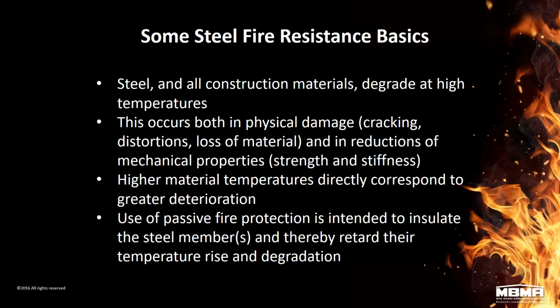It's physically visible damage, such as cracking, buckling, loss of material, charring or an actual burning of wood and plastics. But also the mechanical properties deteriorate, and these are your strength and your stiffness, which are important for the structural performance.